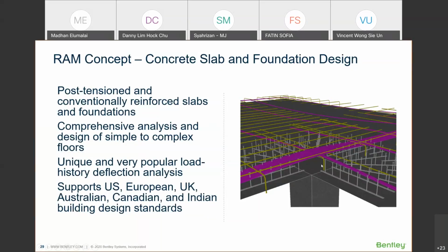So Malaysia, just like Singapore, is not a high seismic zone. In fact, we do not have seismic codes for these two countries. Now that we are adopting Eurocode, EC8 is coming into the picture, but traditionally they are not seismic zones at all. Blessed countries, Malaysia and Singapore. So why I'm talking about this is because flat slabs perform better in non-seismic zones, whereas for seismic zones, the beams are important, like one-way floors and two-way floors.